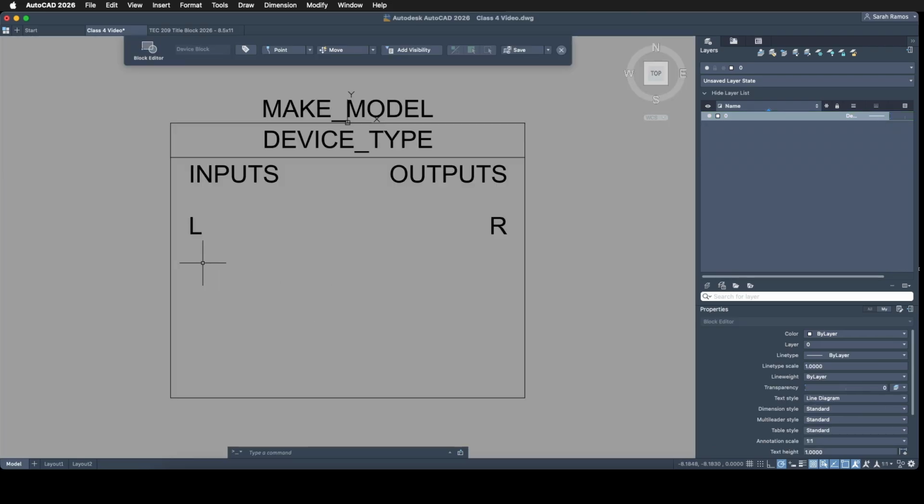So how tall this thing wants to be depends on what kind of equipment it is and what you're doing with it. So we're going to make the bottom line stretchy with one more dynamic setting. It requires us to set a parameter first. The one we want is a linear parameter. From here to here in the middle. It doesn't stretch yet. We will want to then add a second thing called an action. We want stretch. I'm going to click on stretch, apply it to my linear parameter by clicking on it.